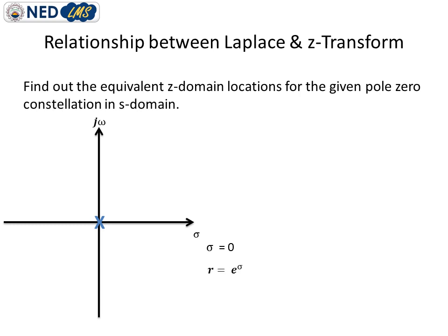By utilizing this information, I can calculate the radius of the circle as well as its angle. Angle is very simple and straightforward. As omega is 0, omega is the same in the Z plane as it is in S plane. So omega is 0 in the Z plane also.